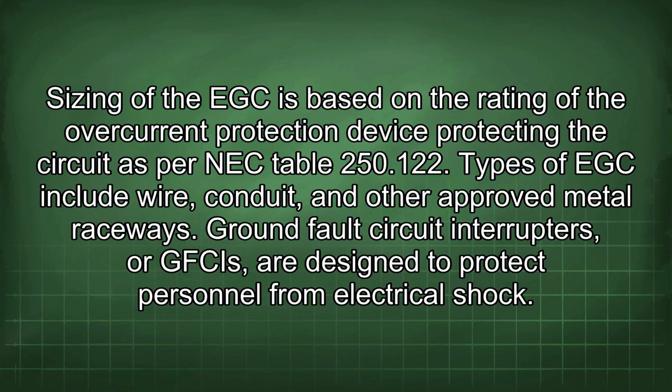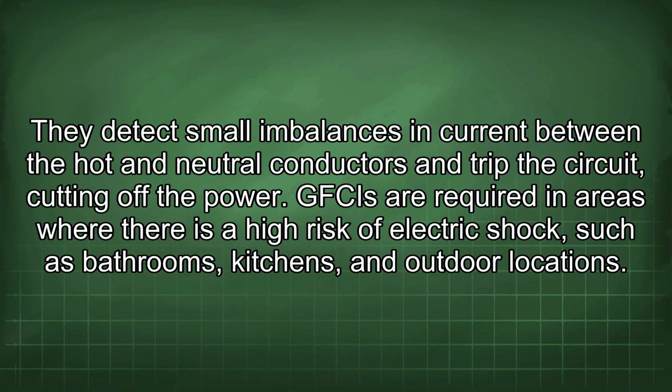Ground fault circuit interrupters, or GFCIs, are designed to protect personnel from electrical shock. They detect small imbalances in current between the hot and neutral conductors and trip the circuit, cutting off the power. GFCIs are required in areas where there is a high risk of electric shock, such as bathrooms, kitchens, and outdoor locations.